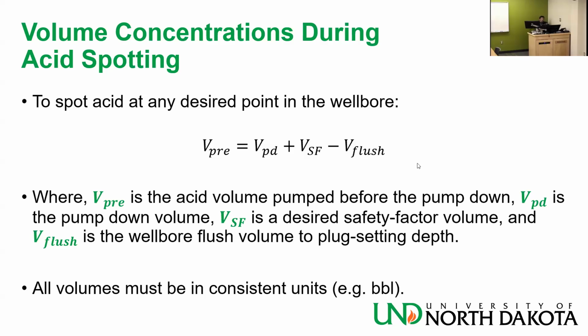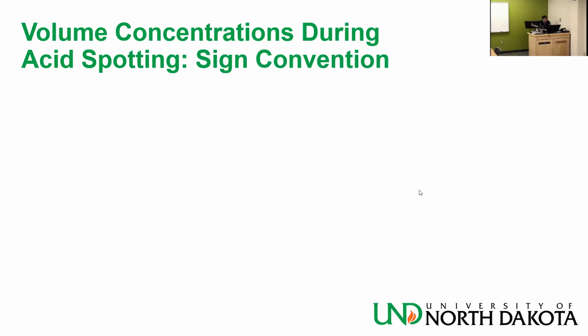All volumes must be in consistent units like barrels, abbreviated BBL. Volume concentrations during acid spotting. Let's do a little bit of sign convention. You have fluids going in the well, downhole, and fluids coming out. You need to take both into account.